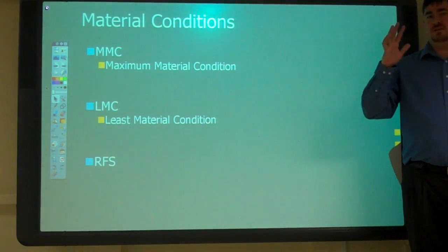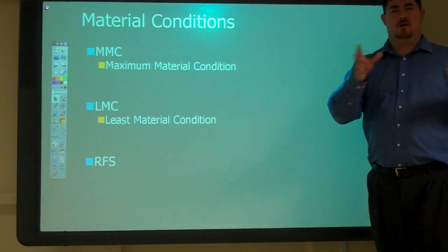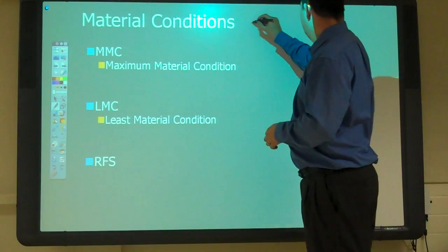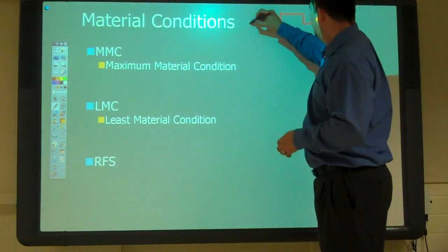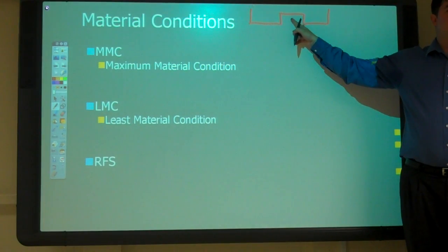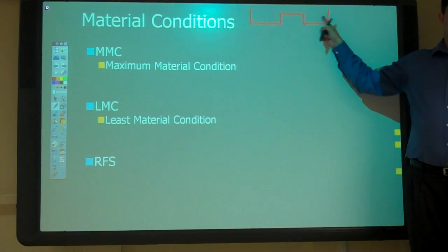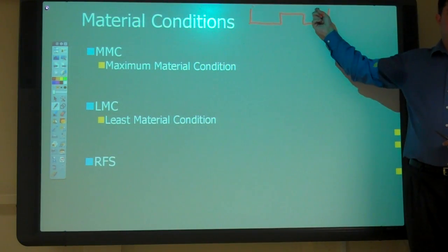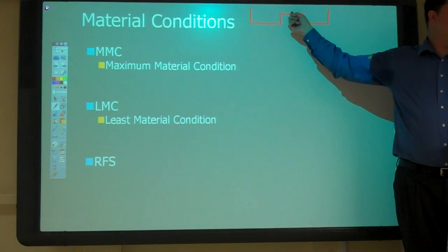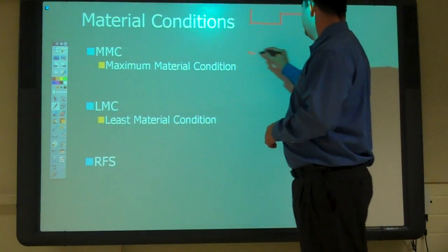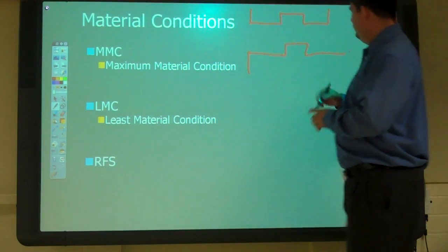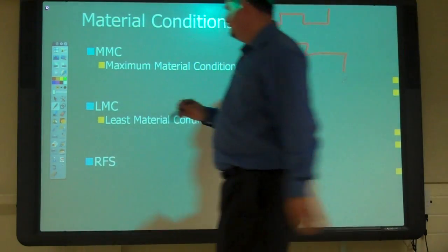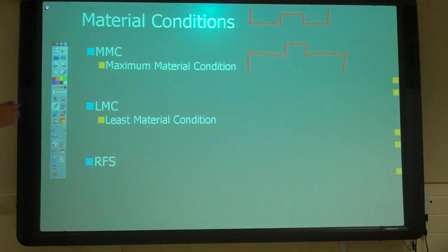So when we're talking tolerances, like last week, we always talk about holes and shafts. But it could be slots and things that go into slots. So a slot would be the same as a hole, right? This piece here would be the same as a shaft, right? Because this is going to go into something else. That'd be considered a shaft. That would be considered a hole. Now this is the shaft and hole, same thing as if it was round. The shape doesn't matter if it's male or female, basically.